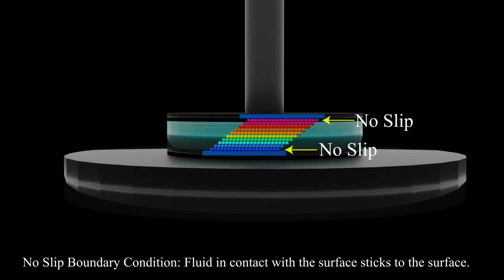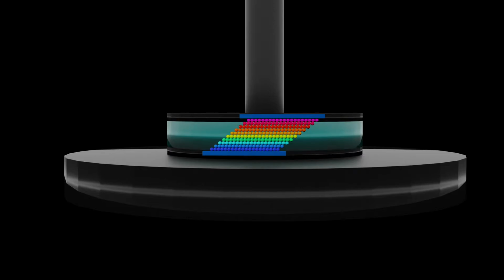The type of flow produced by the rheometer is known as a shear flow. In a shear flow, the fluid is assumed to move only parallel to the plates, and the velocity of the fluid increases perpendicular to the flow of the fluid. After taking several measurements from the rheometer, a graph showing shear stress to velocity gradient can then be made from the measured values.